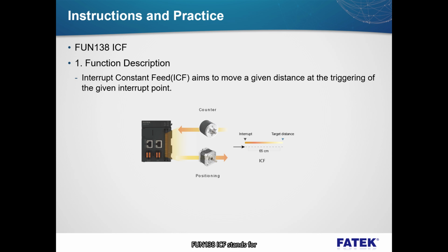Function 138 ICF stands for interrupt constant feed. After enabling a FUN 138 on a given axis, the axis will rotate towards a given direction at a given constant speed, and then stops after moving for a given distance when a specified interrupt source is triggered.